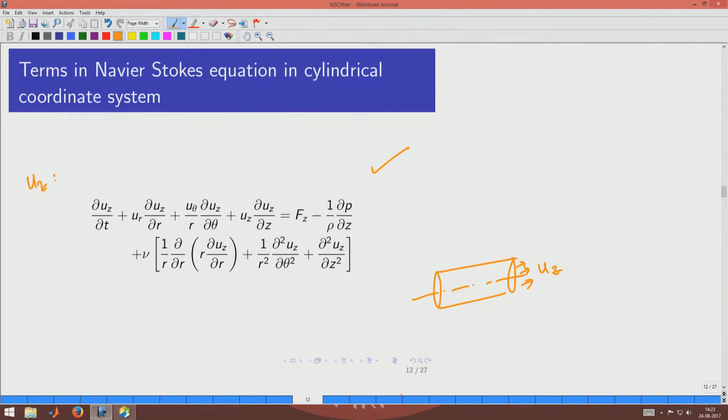For each problem we need to observe which component I want to solve the velocity for, and then bring those equations onto the board. Sometimes we may require multiple velocity components, but very often, if you can simplify the problem using symmetry arguments and aligning the coordinate system appropriately, and reduce the number of velocity components to 1, then analytical solutions are available.